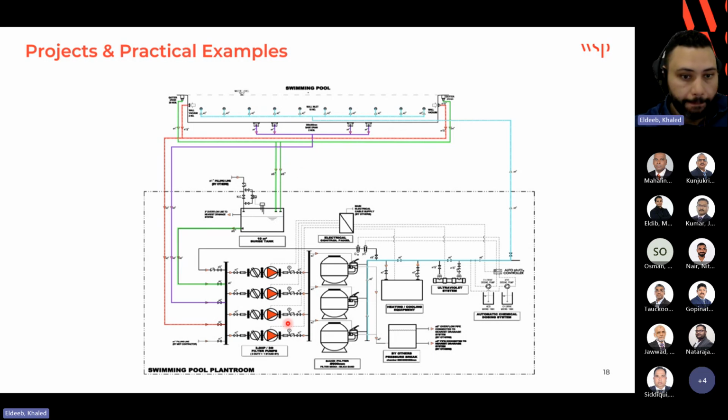The level of the equipment room has to be lower than the lowest level in the basin of this pool. And one more thing, if you remember, I told you the chlorine could be gas. If for any scenario you are required to use a gas cylinder, it is toxic and has to be treated carefully.